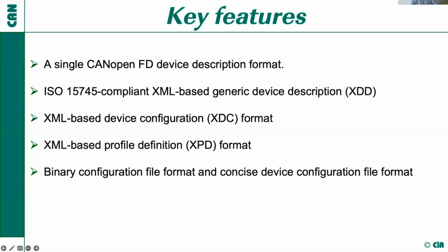Key features of device description were approved by one of the working groups that my colleague and our director, Mr. Zitzmann, already presented. CANopen IG decided that we need for CANopen FD devices one single description format. It should be XML based, ISO 15745 based as its predecessor.